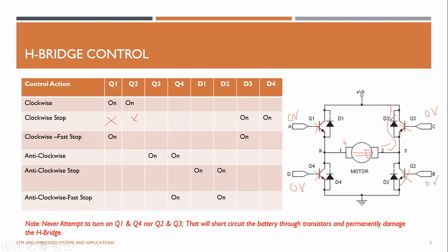So the current can go through this diode, through the VS. And so this is acting as a battery. Go through the battery and come back to the ground and come back again. It cannot go to the same point where it started. So it has to go to this point, right? So D2 is not an option. So it can go through D4 and come back, making this circuit complete. So it has to go through by charging the battery.